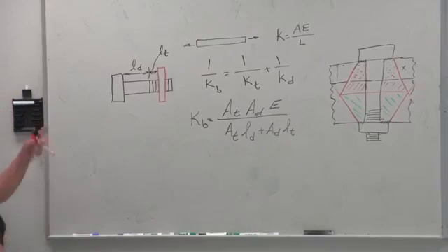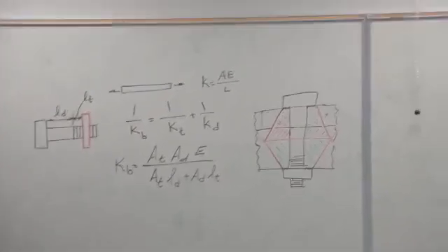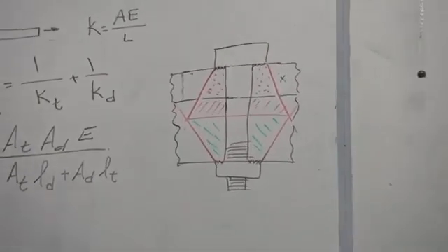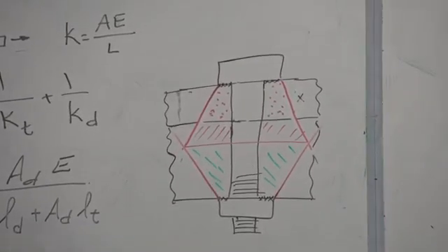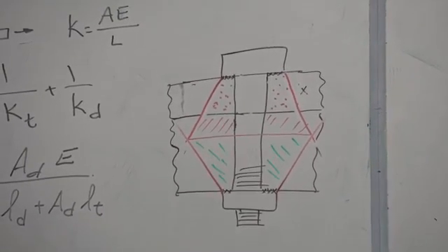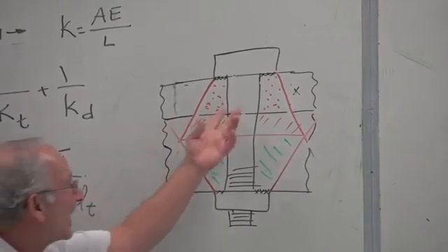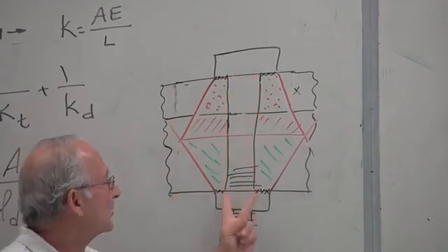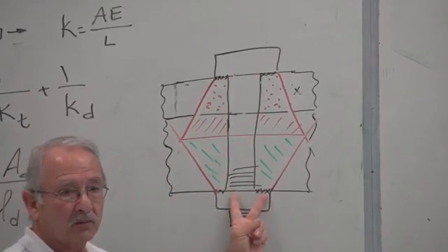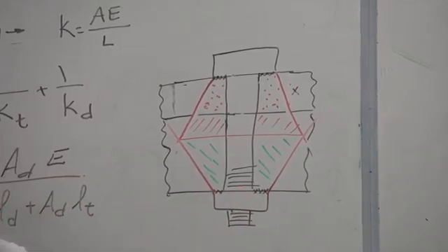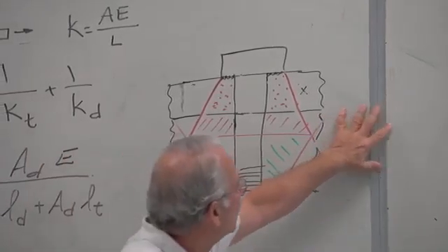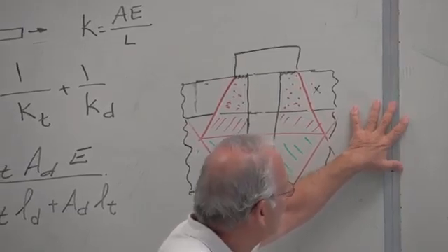Any questions about that picture on the board? That is the path through which the load is assumed to be transferred or connected from the underside of the bolt to the top of the nut, going out somewhat. Once you get out here, it diminishes appreciably.